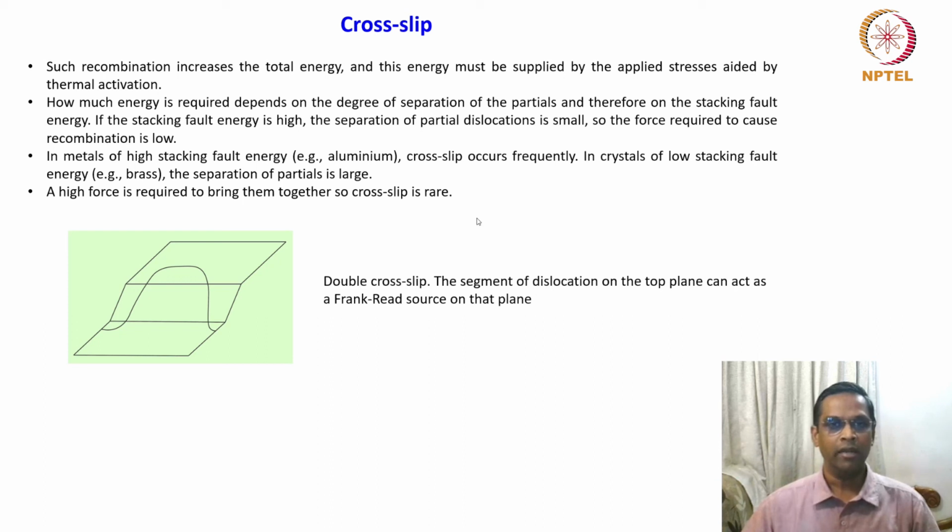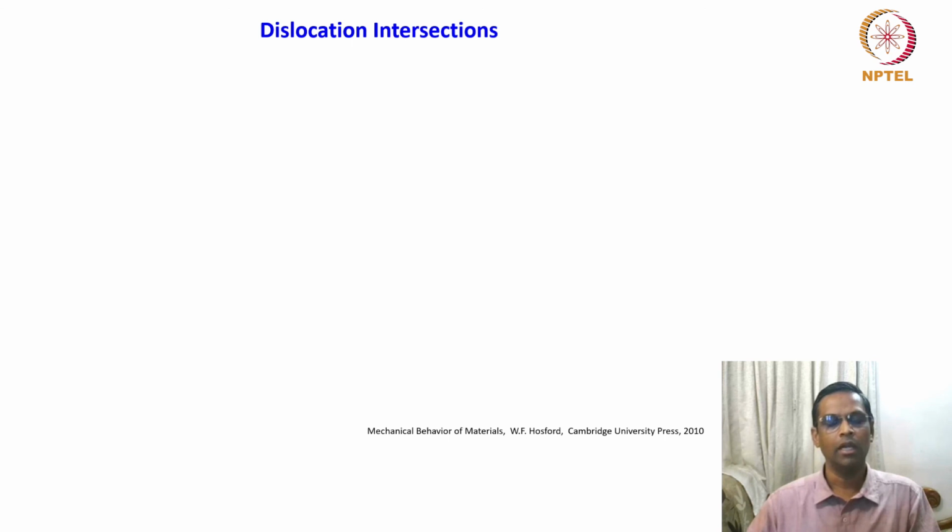When the three-dimensional mobility of dislocation is facilitated, then the dislocation will move through cross slip very easily, and you will see all sorts of dislocation morphology, long extended dislocations, like tangles and cells and so on. We will see this when we come to the description of the deformation structure.